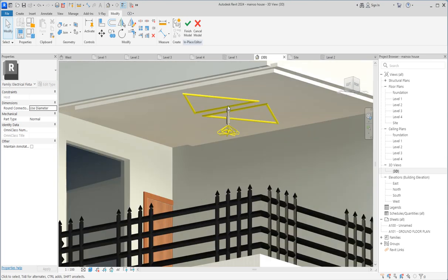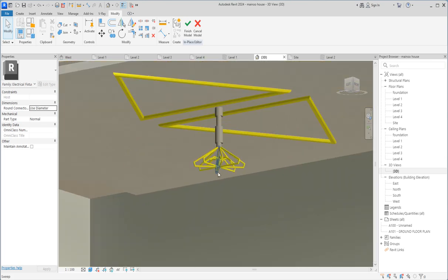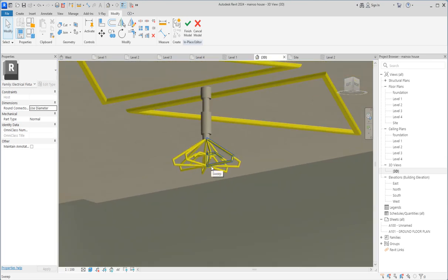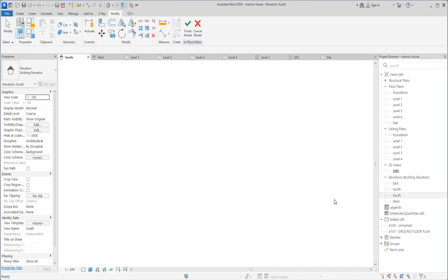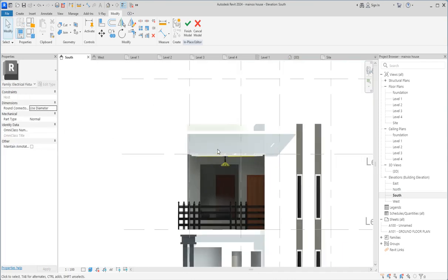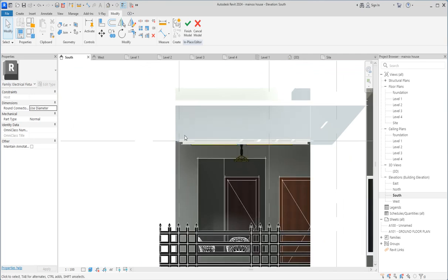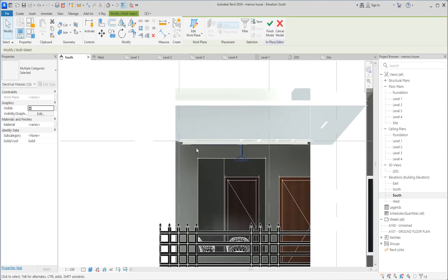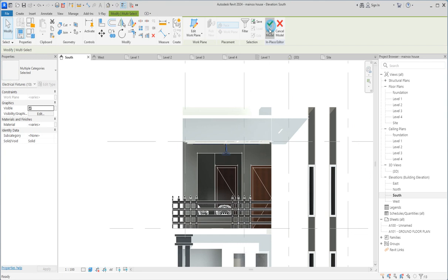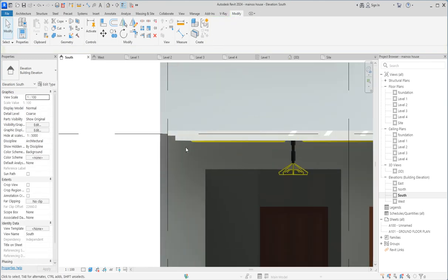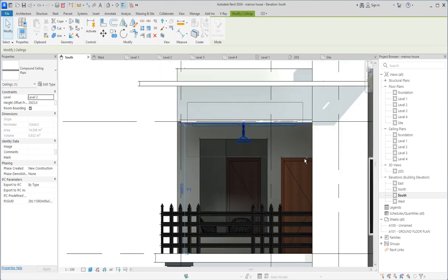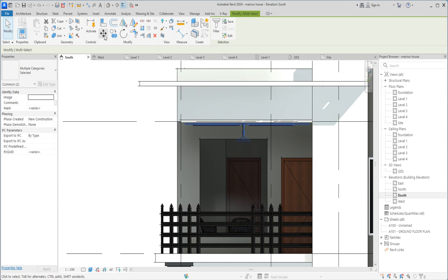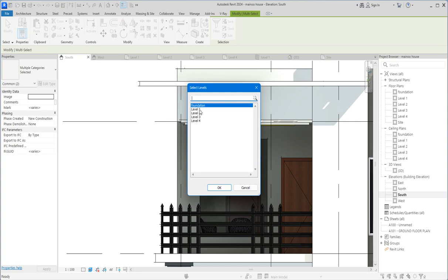So the same thing, you can copy this one now and use it as your whole pattern and bring it to the relevancy of the design you have done. So that is what I just want to do at this particular episode. So the pattern of the lighting, which I'm going to select now, and I will say finish it. So copy the same thing, copy everything you have here, and you say copy to clipboard, then select your level, which is level 1.